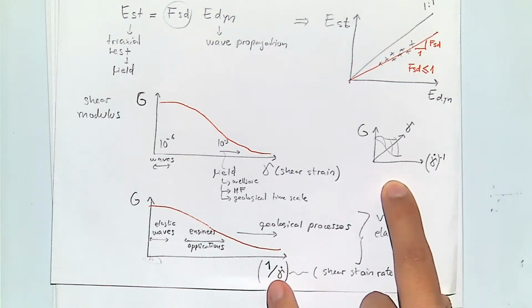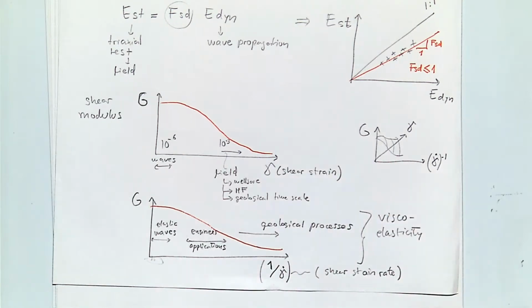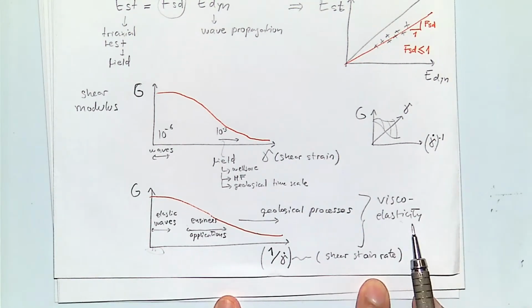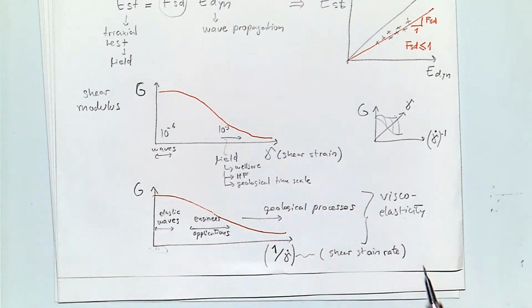So we're going to add that level of complexity later on. But that also adds some viscoelastic behavior that results in these variations of shear modulus, or also bulk modulus, as a function of the velocity of loading or the strain rate. So this reasoning will be only applied for the S waves, for example? Correct. For the S waves or, in general, for the shear modulus or anything related to just the mechanics of the rock without taking into account the fluids inside. Yes.